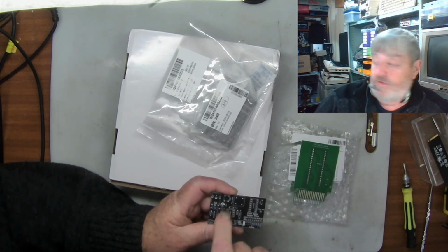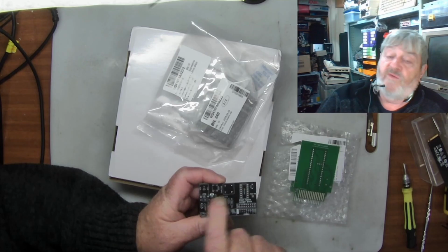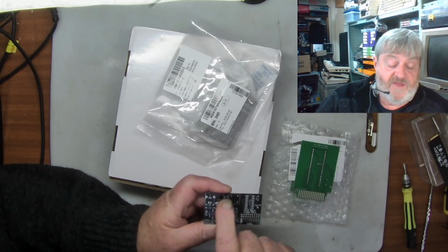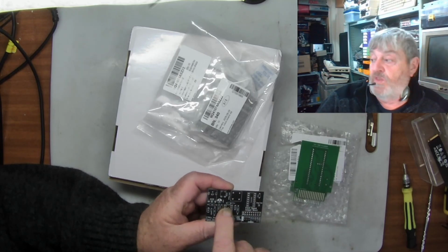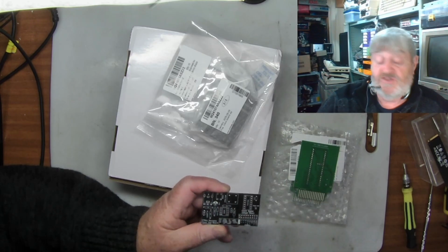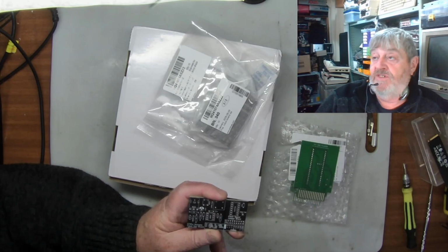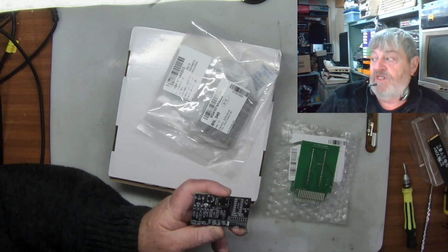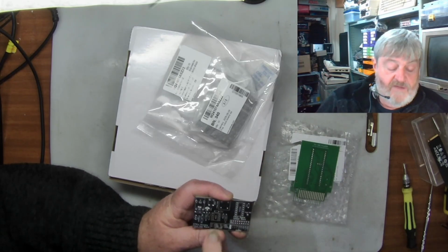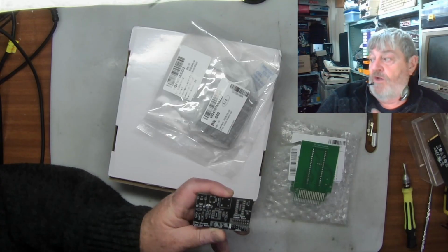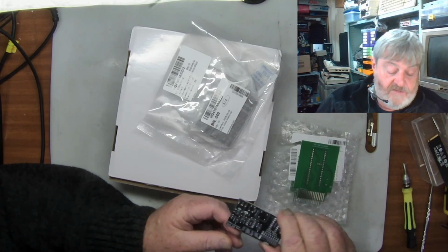Now the other circuitry is on here. Someone asked me what the 555 timer and all that is for. That stuff goes along with the reset switch, and that is for doing the reset circuit. You push the reset button, and to reset a Z80 processor it needs so many cycles before it can kick off again, and that's what the timer does. The timer counts down to give you that time.